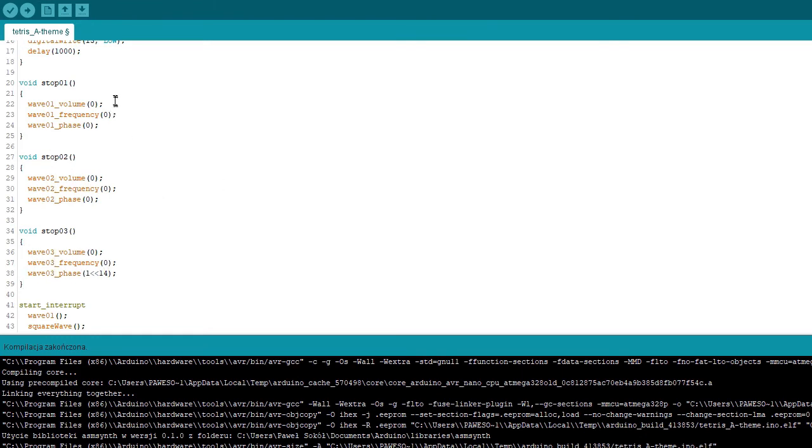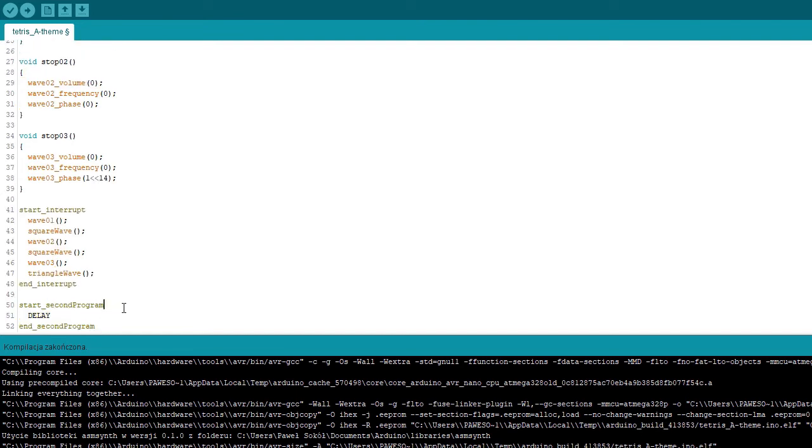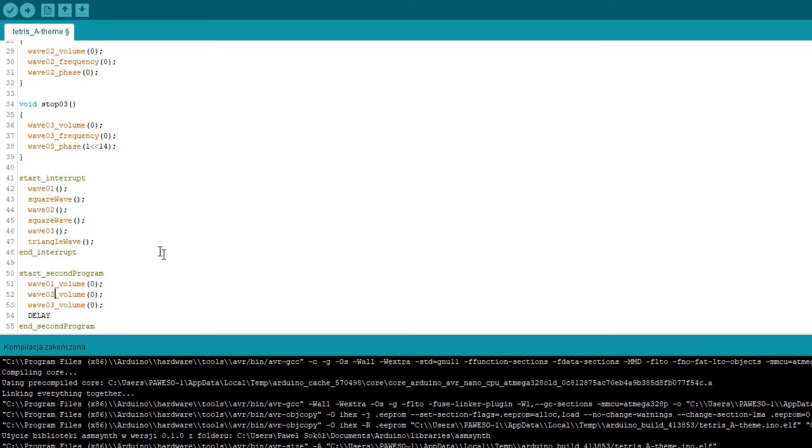Now we come to writing the Tetris theme. By default, all waves are set to 0 volume, so you need to turn them up. You have to be careful that the square wave has twice the value as it is counted twice. The sum of the loudness of all waves simultaneously reproduced must not exceed the value of 255. Additionally, it is worth making a certain margin. It is not required, but if you hear distortions or crackles, it is worth turning down these waves a bit.